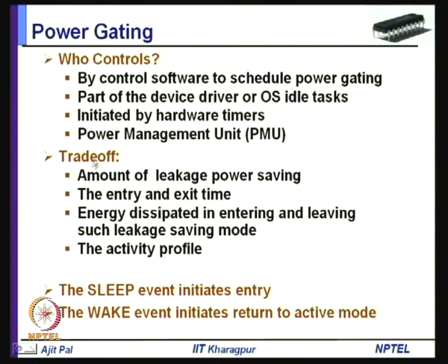That means, the power dissipation you have by not doing power gating should be larger than the energy dissipated in entering and leaving such a leakage saving mode. Then there is also a trade-off with the activity profile. Based on the activity profile, you have to judge whether you will be doing power gating or not.